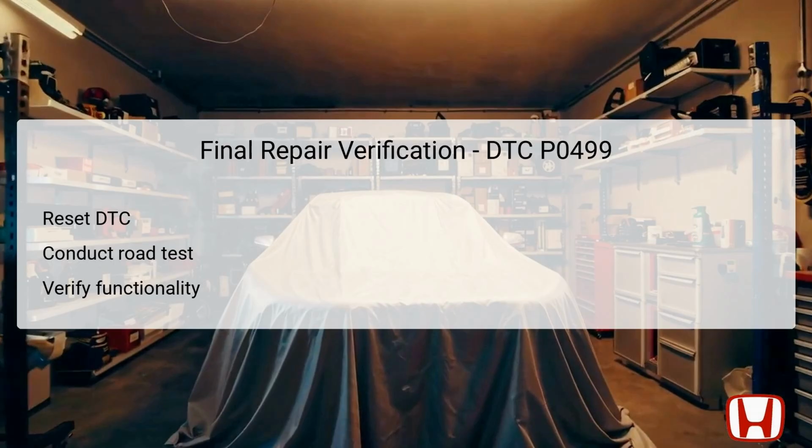During this road test, the technician needs to observe the vehicle's performance, particularly focusing on aspects of engine performance and emissions. Finally, a post-repair diagnostic check should be performed to confirm that no codes have reappeared. This thorough verification process helps guarantee that the problem has been completely resolved and that the vehicle will operate correctly moving forward.